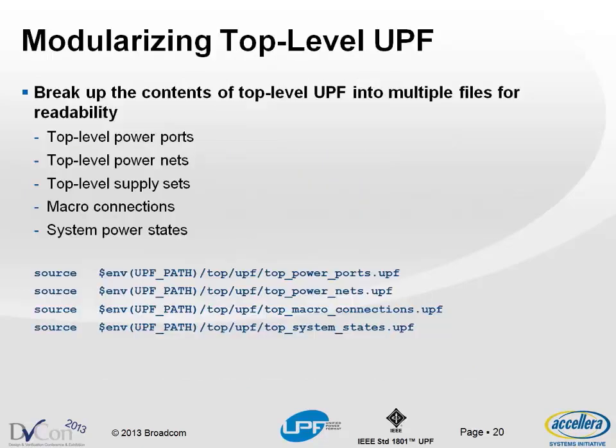Modularizing a top-level file. Once you start having lots of power domains and you start putting all these power ports and system-level power states, your file is going to grow really large and it's going to become unreadable. Just like you would break up your HDL into more readable chunks, you'd like to partition your UPF file into more readable and easy to understand chunks as well.